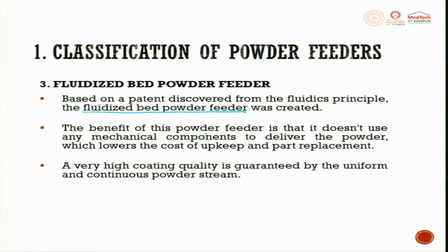The benefit of this powder feeder is that it does not use any mechanical component to deliver the powder, which lowers the cost of upkeep and part replacement. So, if there is wear and tear in the powder feeder, then the amount of material which is getting dispensed will not be controlled. So, the quality of the output is a big difficult task here. So, fluidized bed powder feeders are very much used, because here it is predominantly air that drives it.